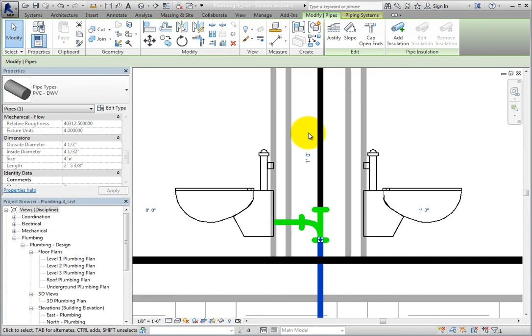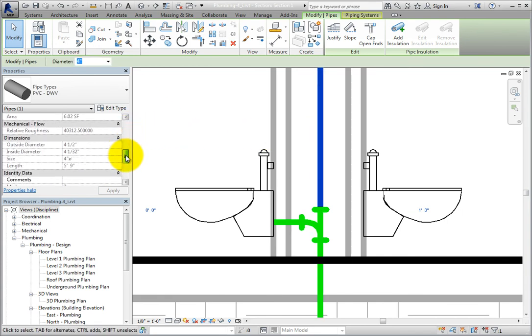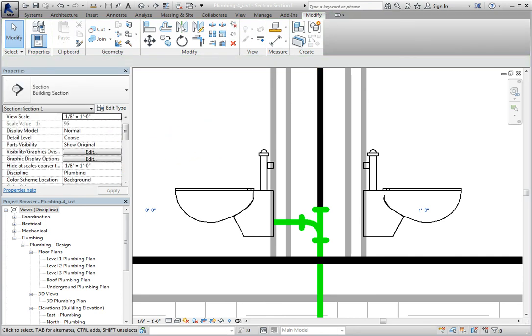When I select the vent pipe, it does not even have a fixture units parameter. There is not actually any flow in a vent pipe anyways, but vent piping is sized based on the flow through the sanitary system. If you want to calculate flow in vent systems, you will need to build your own custom families.